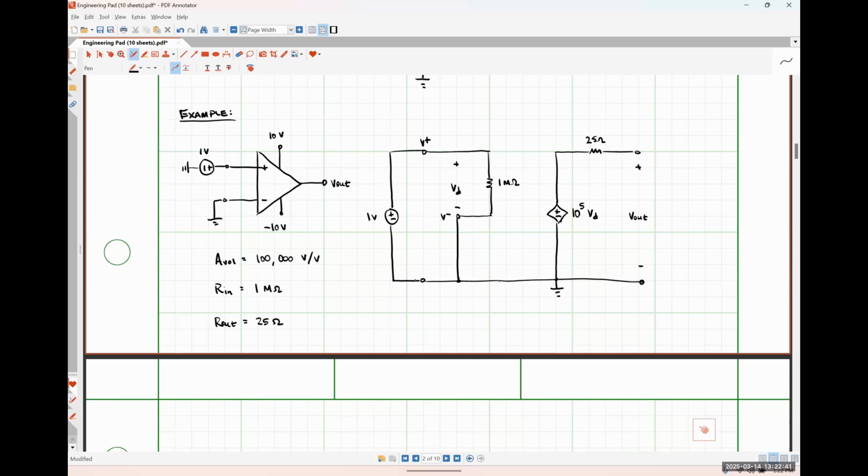For what it's worth, when I do this, I always start with the practical op-amp model itself and then make all of the external connections. When we get into negative feedback circuits, I might flip that input resistance over, putting the inverting input terminal on top, just because it's slightly easier for me to draw the feedback connections that way. It doesn't change anything as long as we always put the positive polarity terminal of VD on the non-inverting input side and the negative polarity terminal of VD on the inverting input side.